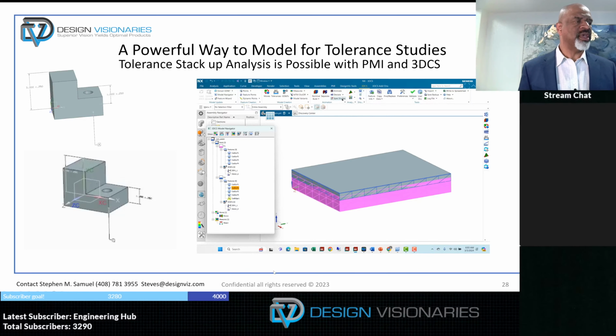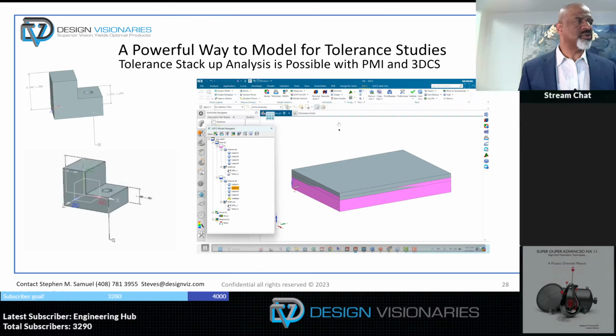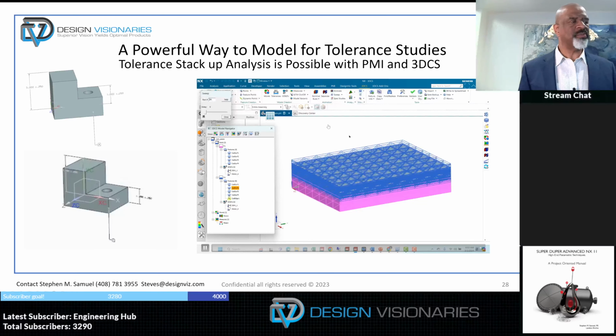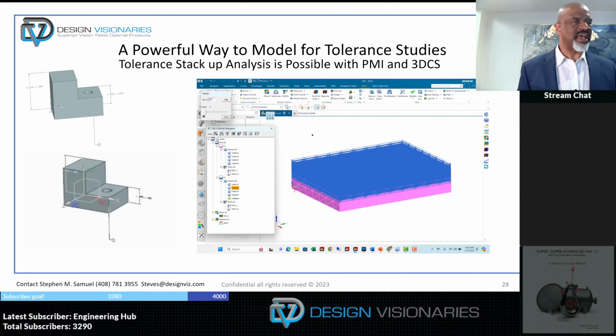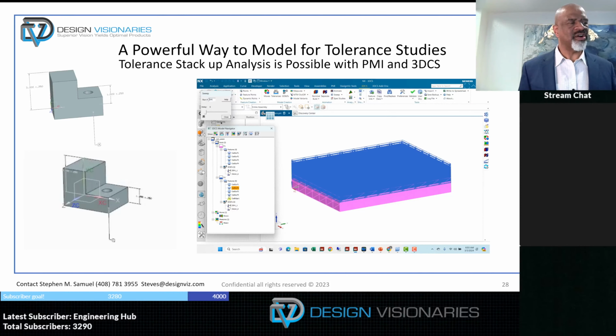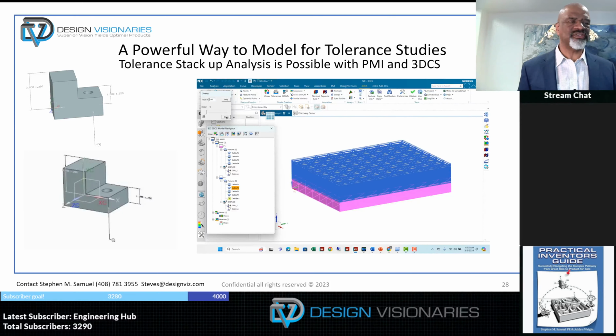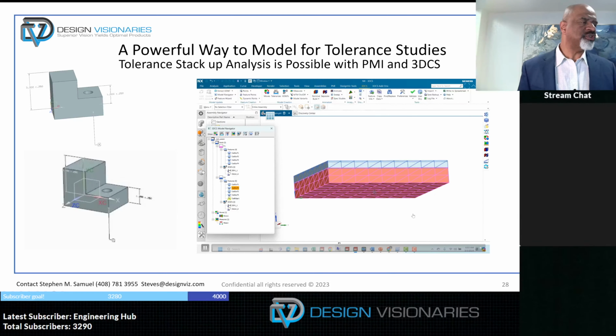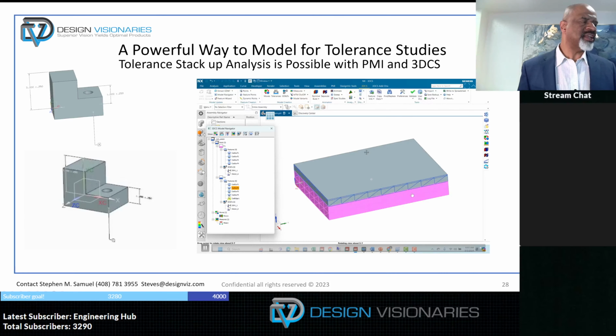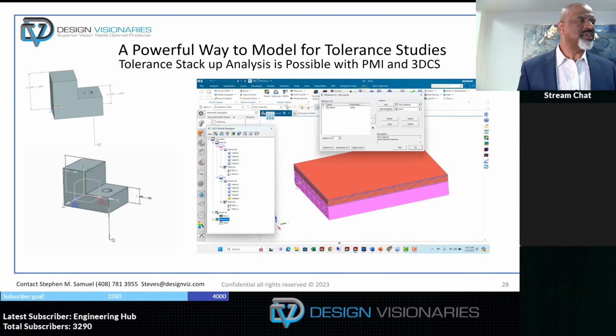That's awesome. And then what you can do is a thing called deviate or sweep, where you can actually see in a mesh format exactly what's going to happen with the components as the tolerances are applied to the assembly, not just the individual components themselves. That's amazing. And then you do this thing called a measure, which allows you to figure out what kind of dimension scheme you would want between the stack-up of different parts, and you give it your limits.